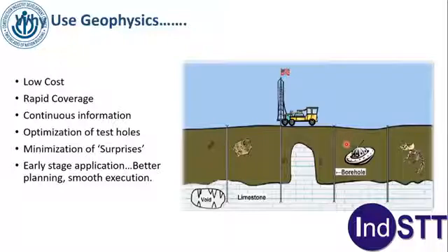And the geophysical solution for that? The integrated approach of subsurface utility engineering. Now, I'm not going to cover SUE in this particular lecture. There is a separate lecture for this. But the approach of SUE is what is used to find out where the existing utilities are, and that gives you the safe bore path. The tools which are used are GPR, induction locator, acoustic locator, gas pipeline locators, magnetometers, EM surveying, etc. So there is a sure shot solution for the first objective.